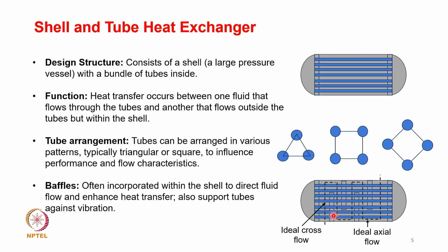Another application of baffles is that, since you are pumping the fluid through the shell, in order to avoid any vibrations of the tubes, the baffle acts as a kind of resistance. So first of all, a baffle will help you give a direction to the flow, and it will also help the heat exchanger to withstand the high pressure flow.